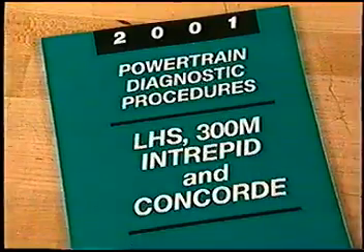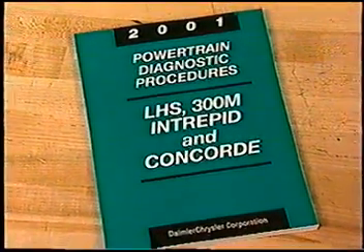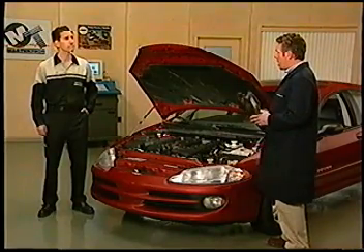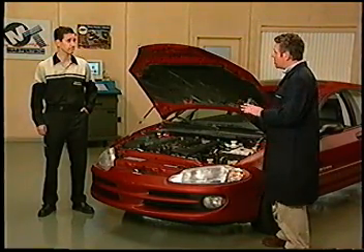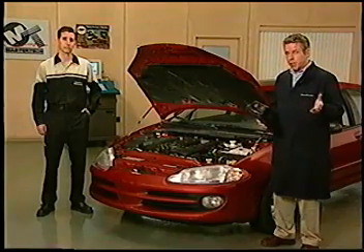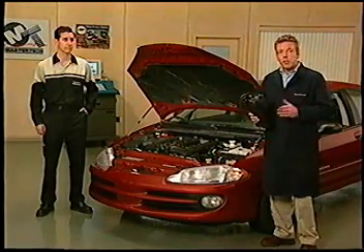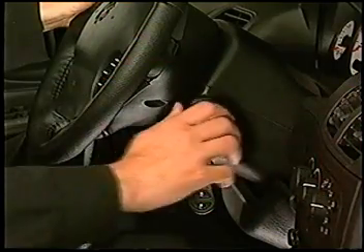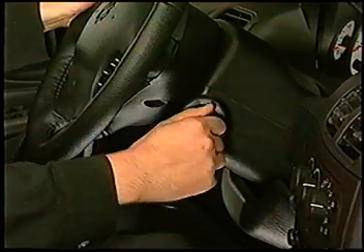If you still can't find the cause after checking the gas cap, hoses, and connections, you should then refer to the diagnostic procedures for further assistance. I think in this case the cause may have been the loose gas cap that you tightened. But the PCM has not run 3 good trips on the evap system yet. So using the DRB3, let's observe the monitor to see if it passes. To do this, we'll have to start the engine.